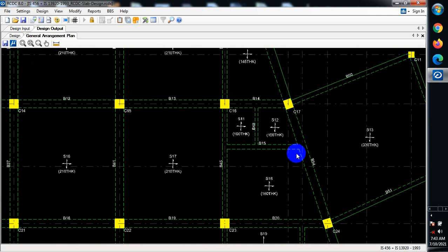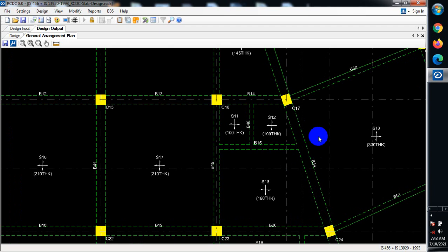And then there are cases whereby you may not want to tamper with the architectural drawing, because in the architectural design this particular area might be an opening, maybe like a door. Maybe a door is around here, so definitely when you place a column here, it will become an obstruction around that area.